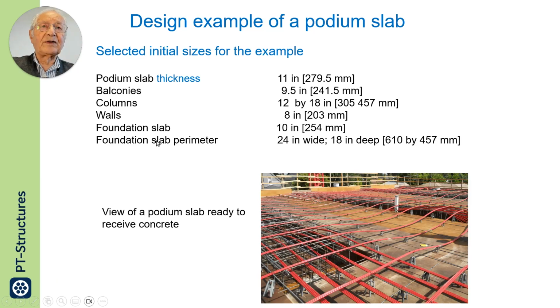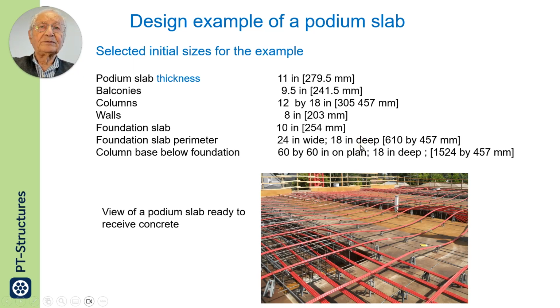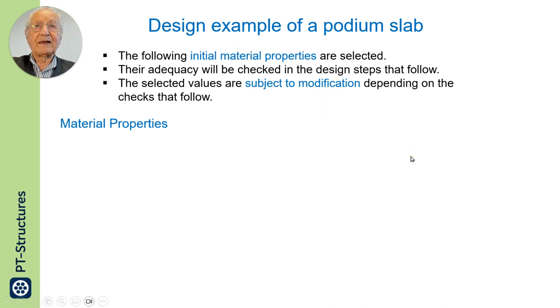Perimeter of the foundation will be 24-inch wide and 18 inches deep. Column base below foundation will be a pad, 60 by 60 inch pad, 18 inches thick.